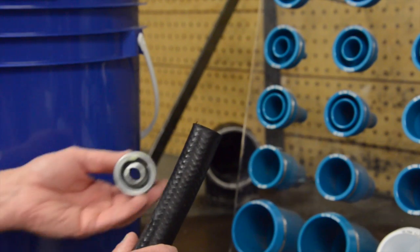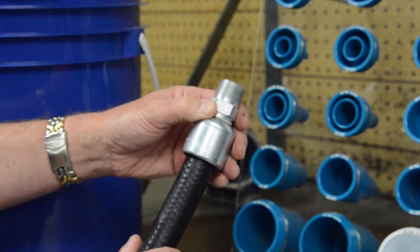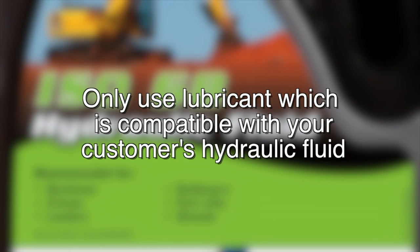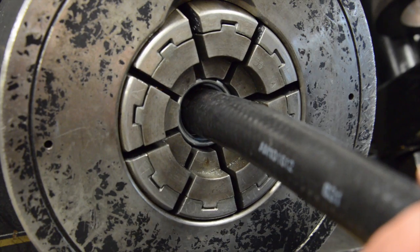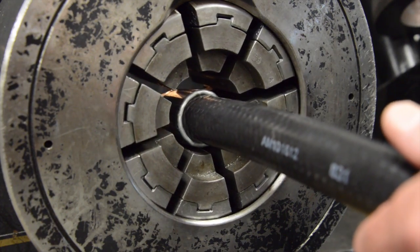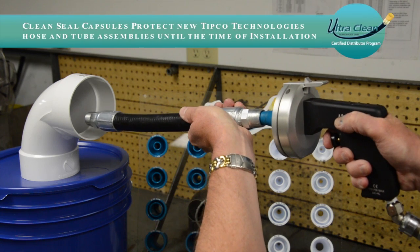When crimping or swaging the end connections onto the hose, do not lubricate the stem of the fitting with lubricants that are not compatible with your customer's hydraulic fluid. This would recontaminate the hose you're cleaning. Use lubricant sparingly and start above the end of the stem. The crimping or swaging process causes stem deformation to achieve the proper coupling retention. Internal metal flash contamination will occur, and it must be removed. A third and final projectile must be fired through the entire assembly to finish the cleaning procedure.